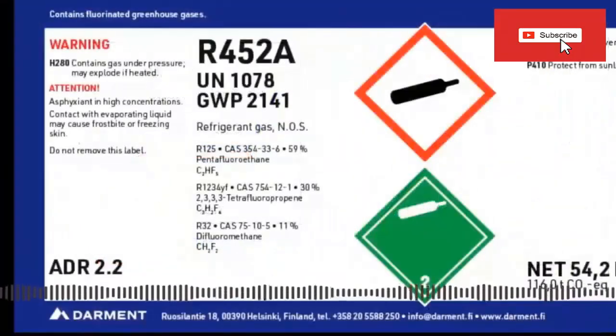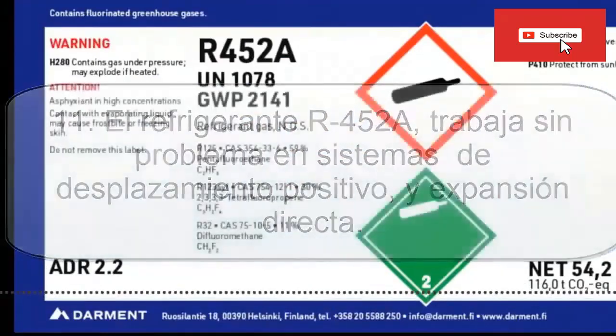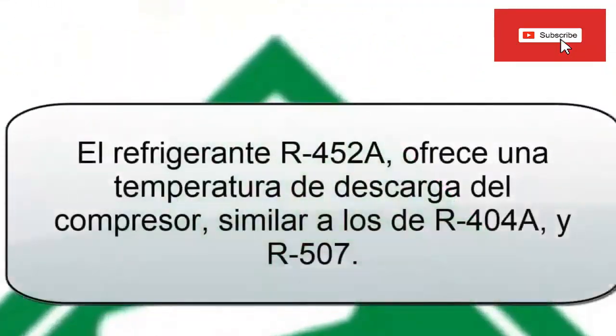10. R452A refrigerant is only compatible with POE type synthetic oils. 11. R452A refrigerant works without problem in positive displacement and direct expansion systems. 12. By having mass flow rates similar to R404A refrigerant, R452A refrigerant eliminates the need for thermal expansion valve adjustments. 13. R452A refrigerant offers a compressor discharge temperature similar to R404A and R507.